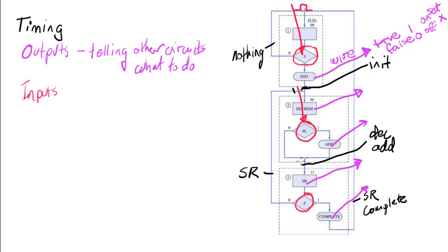Z has to be set up right here and it's looked at on this clock tick, not on the clock tick out. So in our algorithmic state machine, it looks at our inputs, adjusts the outputs, and then leaves on a rising edge of a clock where actually shift right and complete happen. So these have to be set up before the transition to where they're looked at.